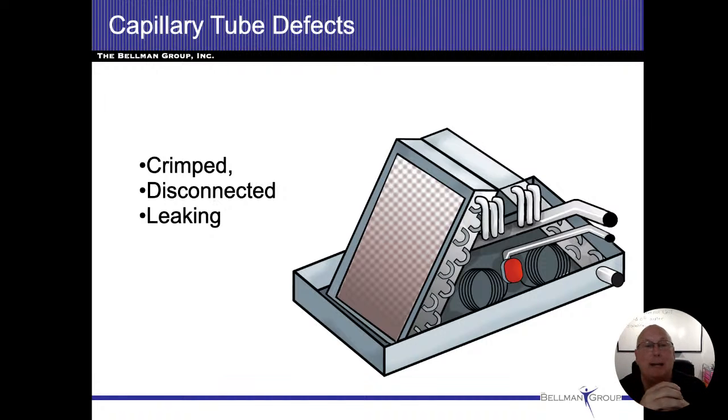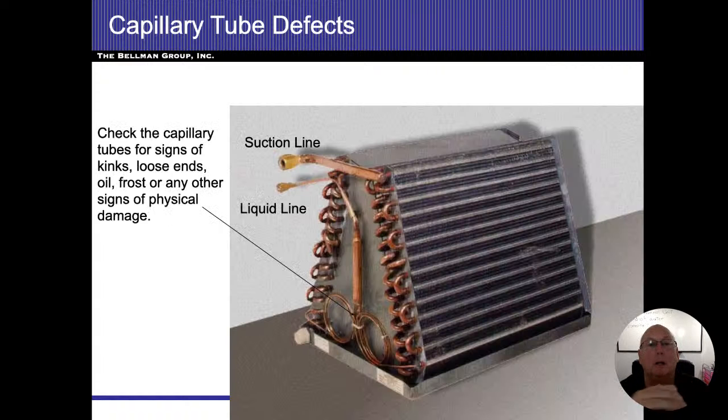So if we ever get inside, and sometimes you'll see a panel on the indoor coils, so you could pull that panel off. Sometimes you can see it when you remove the humidifier, and you can look for these coils. Typically, we don't find too much going on with them, but if they're leaking, and you'll see that with signs of oil, but we wouldn't get our temperature changes anyway, or dented or damaged in any way, we should photograph them and document that as well.